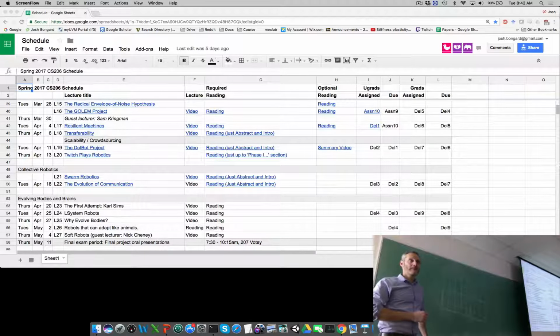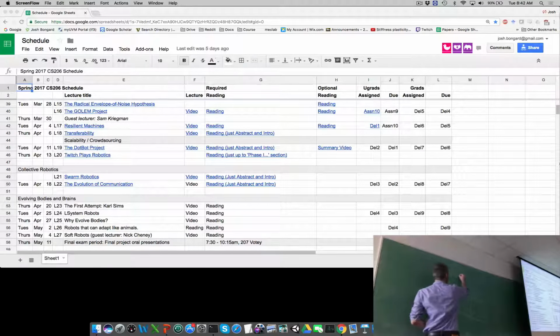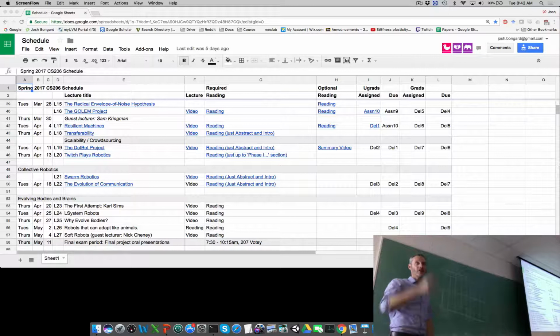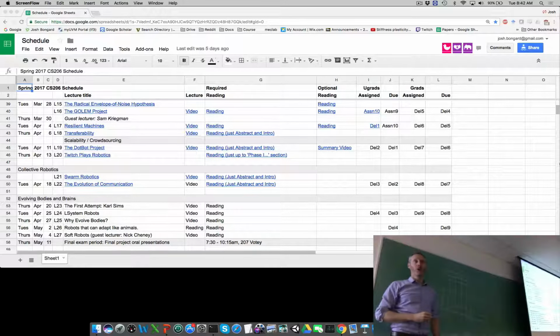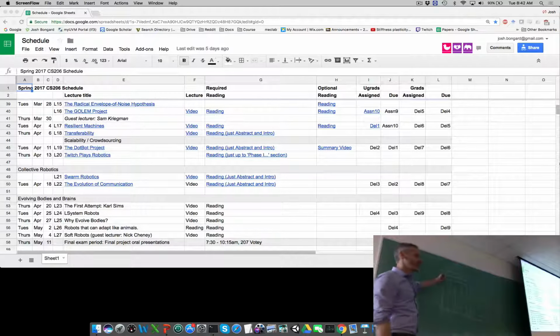There would have to be time steps where all 4 touch sensors are reporting 0. Right, so we're looking for subsets of a row that are all zeros, or what else? Or all ones, right? If it's hopping, some of the times all 4 feet are off the ground, and sometimes we're looking for subsets of rows in which there are all ones. So we could create a fitness function that returns an integer, which is the number of rows that match this pattern, either all zeros or all ones.